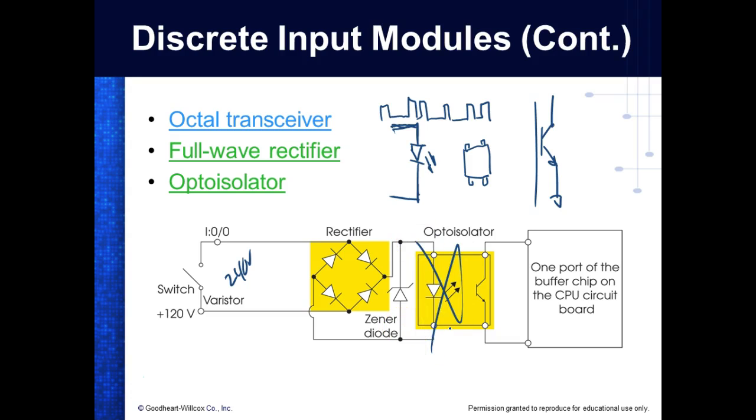But if I had connected this directly into my PLC, that 240 volts would have burned up my PLC, and now I'm screwed, right? If it just wipes out that little optical isolator, then if I kept a spare input port, I can just take a wire that was plugged in over here and move it over to another input. But now you have to change your program.